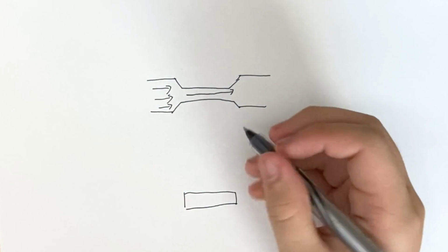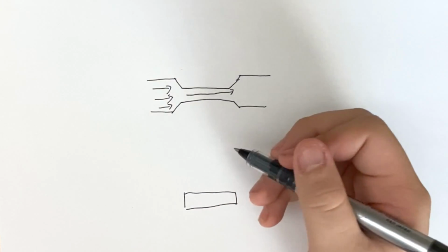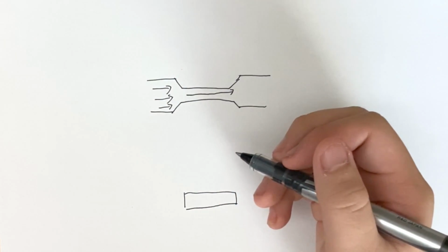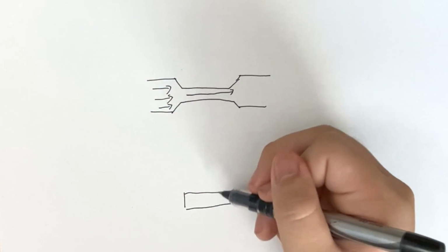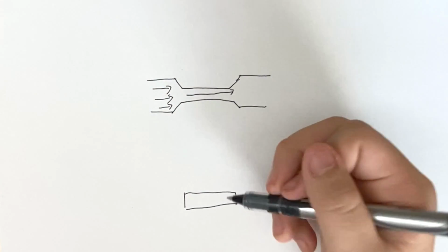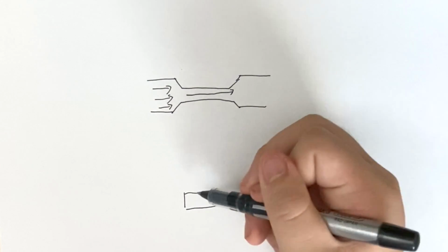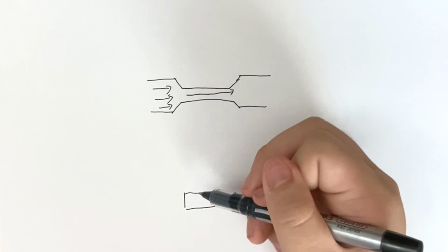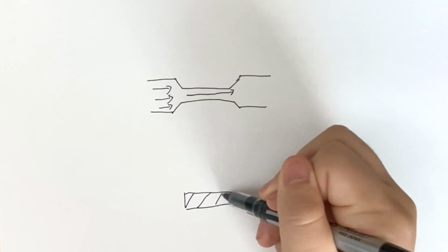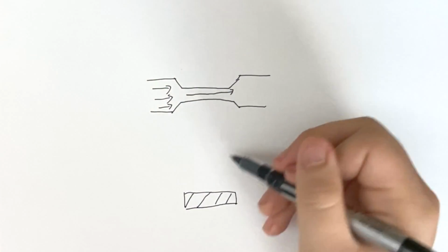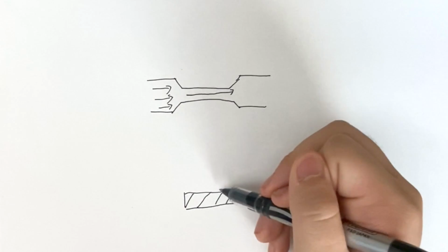And then this tube is coated with carbon film, or metallized coating if it's a metal film resistor, to a certain thickness. By controlling that thickness, people can control the resistance of the resistor. You can also tune the resistance of a resistor by cutting a spiral into it. Then this creates a path for the electrons to follow.